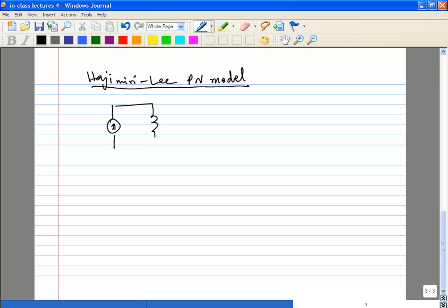The basic idea is, let's say even take an LC tank, you inject some noise into the tank at different points and find out when the system is sensitive to noise, to create phase noise.